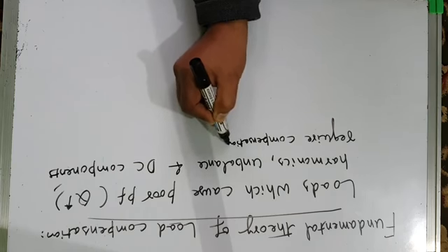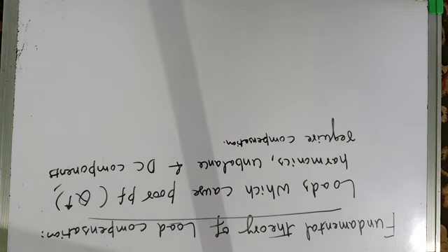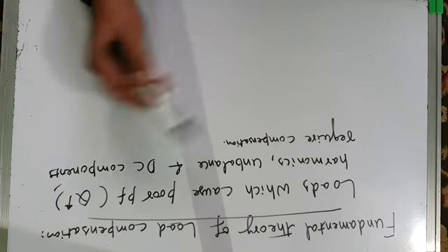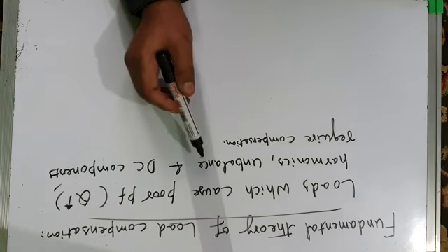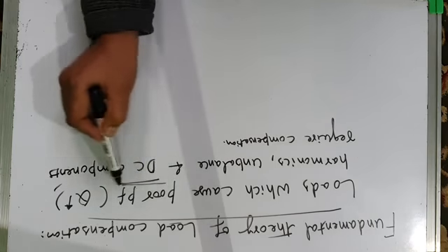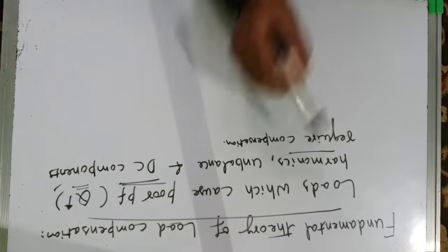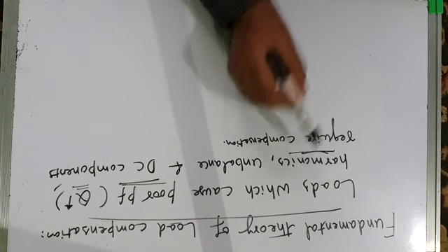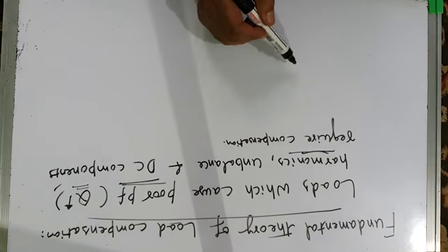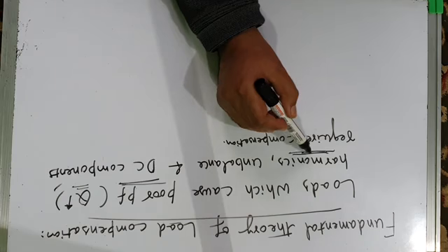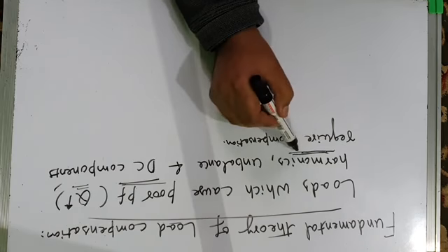You don't need to compensate your generation system, because that is perfectly balanced and sinusoidal. It's the load which causes all these power quality problems. Your load may result in poor power factor and hence large reactive power. Your load may be non-linear and hence it will result in the injection of harmonics in the currents and hence harmonic voltage drops, and hence the voltage at the point of common coupling will also become distorted because of these